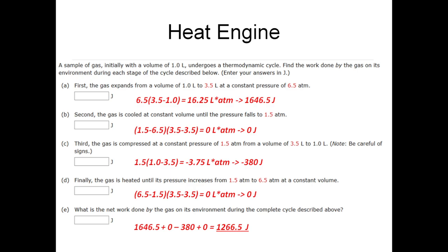The piston is given energy, it expands, it does its particular task. Now that it's extended, there are steps you have to go through to reset it so that it can then perform that initial task again. So, the first step is that the gas inside needs to be cooled until the pressure falls to 1.5 atmospheres. The volume of the gas and the volume of the expanded cylinder isn't changing in this stage. All we're doing in this particular stage is cooling the piston down as its internal pressure changes. The volume is not changing in this step.